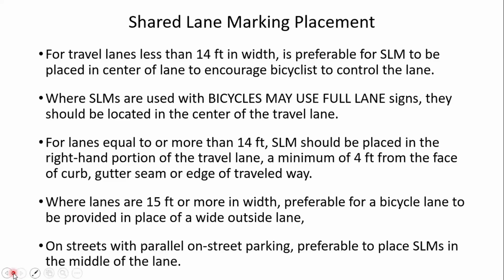For lanes that are equal to or wider than 14 feet, the shared lane marking should be placed in the right-hand portion of the travel lane, a minimum of 4 feet from the face of curb, the gutter seam, or the edge of the traveled way. Where the lanes are 15 feet or more in width, it's preferable for a bicycle lane to be provided in place of a wide outside lane. And on streets with parallel on-street parking, it's preferable to place the shared lane markings in the middle of the lane.